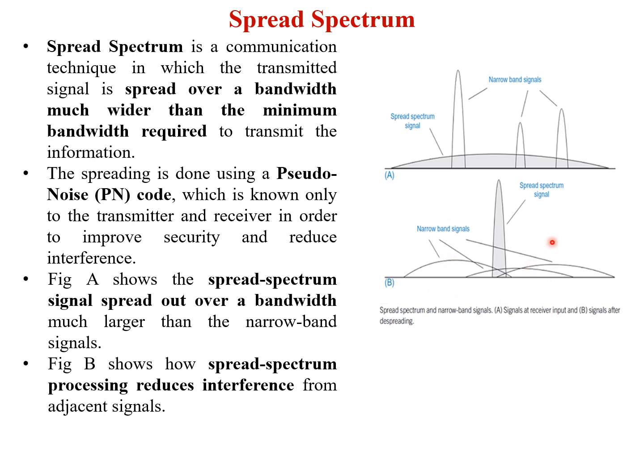And the figure below is despreading. Here most of the power is concentrated in the middle, so the total power of the spectrum signal is in the narrow band, giving a high peak power signal. Whereas the potentially interfering narrowband signals are spread out, so that the power in the bandwidth of the desired signal is relatively low.